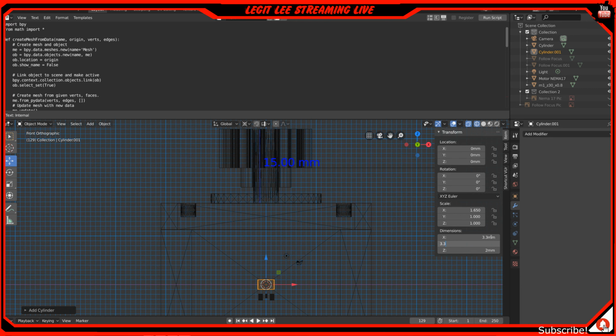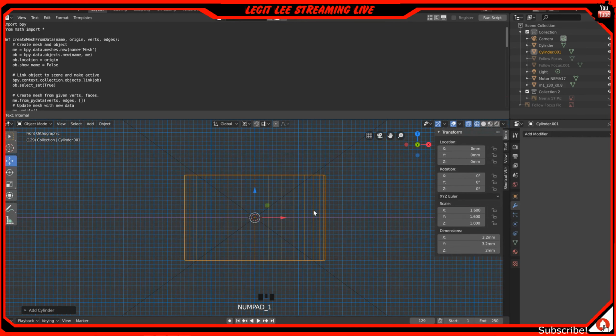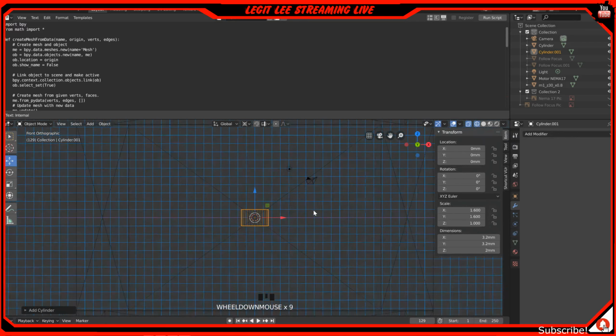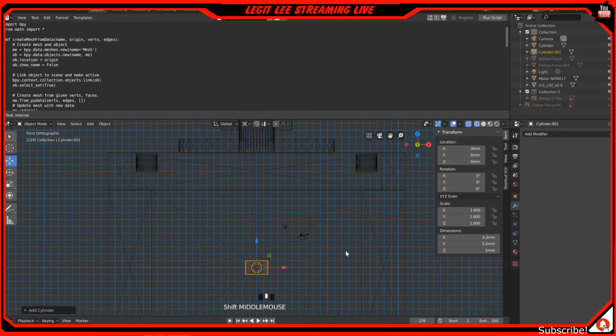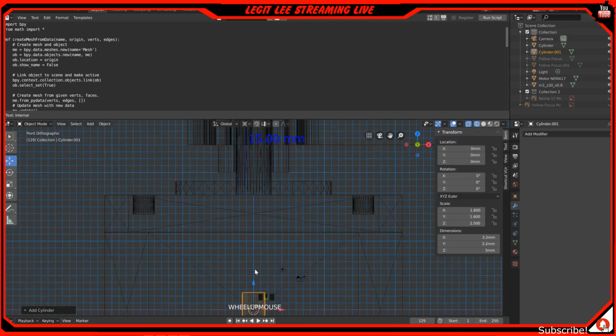The reason why I'm doing 3.3, really I probably should do like 3.2-ish. Yeah, I feel like 3.2 would probably be a little better. All right, 3.2. We're on 3.2, right? And the reason why we're doing that, we need to scale this out to about 5. This is going to be the socket hole, or basically the drilled out hole for our screw to hold on to this nut here. So we're going to drag this all the way up, and about here.